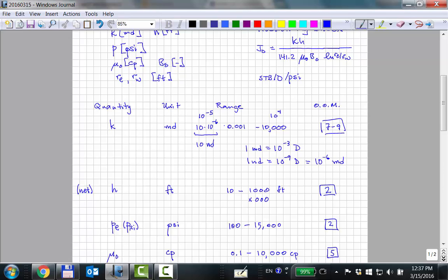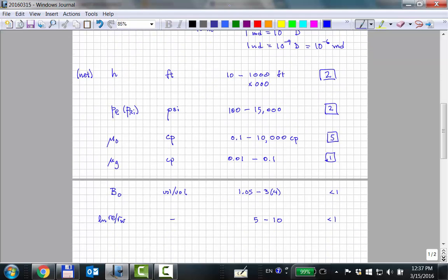That means, for example, like a Ekofisk, I don't know what it is, but let's say that you've got 7,000 pounds initial pressure, you draw it down to 2,000 pounds, that's 5,000 pounds of drawdown at a maximum. Okay, 5,000 times 1 is 5,000 barrels per day. That's good, but it's not great, because some of the wells in Ekofisk could have made 50,000 barrels per day with 5,000 pounds of drawdown. But so 1 is good.